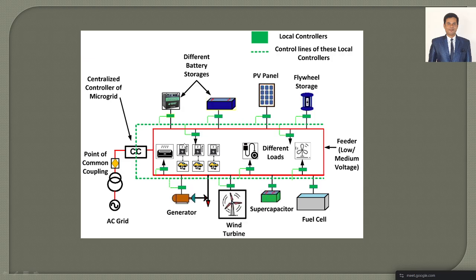Similarly, we also have other components, such as synchronization, right? Synchronization relays. The relay will try to understand when I have to synchronize with the actual circuit breakers. Okay, the relay understands when to synchronize. The relay will try to understand all types of signals. It will try to understand when to connect the circuit breakers and when to disconnect the circuit breakers. Okay, so that is the second component.